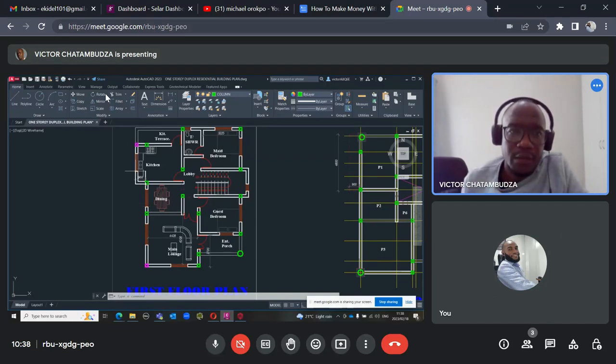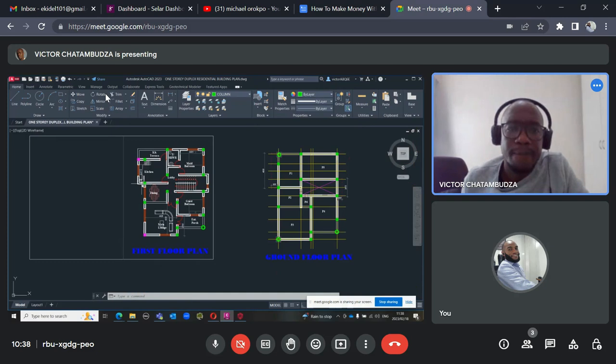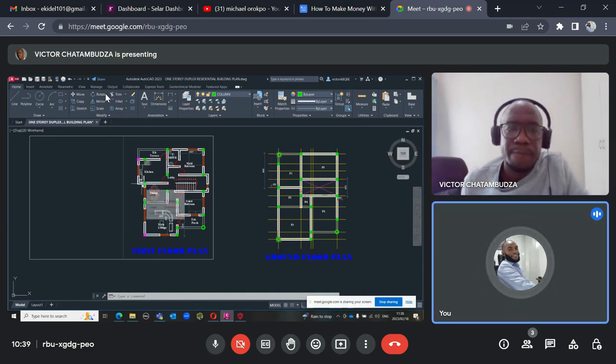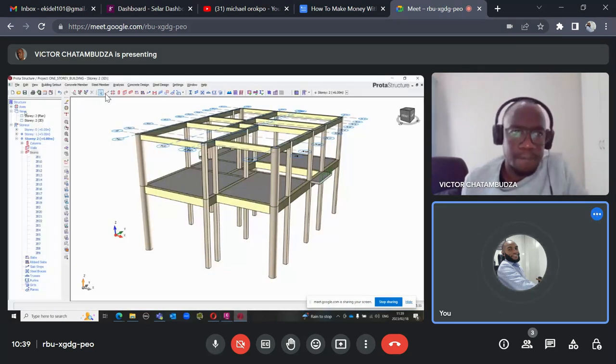Yes, at that point. So right now we are going to model this place and also remove those circular columns which are not in this place. We are going to take out these two circular columns and then model the shape of this cantilever by adding a cantilever. So go back to your model, to your plan view under story 2, plan view story 2.